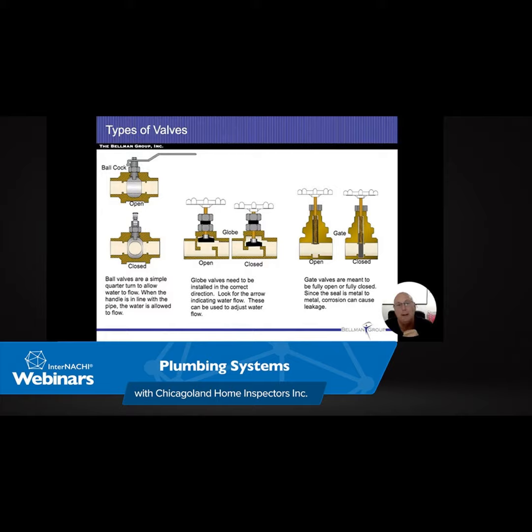Mark was asking me again, why a dip tube on the gas but not on the electric? Yeah, I'm not the expert in designing. I got to make up some assumptions on here. I think a lot of it has to do with the room and the space and the fragility of the dip tube itself. What we don't want to have happen is for that dip tube to break off and fall up against these electric heaters. If we did that, then we would be creating a direct short in the energized portion of the electric burner or heater and the ground if it falls and leans on it. I think that's why they avoid the dip tube on that.